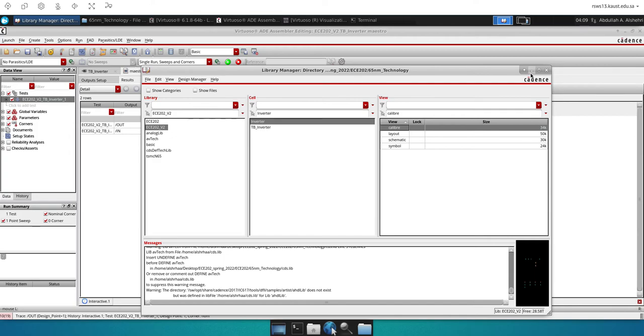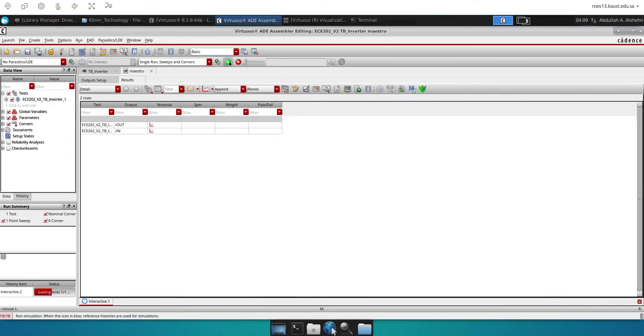We minimize this. Now we need to simulate and compare the design without taking into account the parasitic capacitance, the wire that adds more parasitics and resistance, and after we consider that parasitic capacitance. This is a small circuit, a small inverter, so the effect of this inverter will not be high. But once you have a big circuit, the OTA is considered medium size. You can see how you can design your circuit, because once you do the layout, you need to make sure how big the wire is that you need, and how far from each other. Also, there is parasitic between layer and layer, like floor and floor, not next to each other, but on top of each other. So you need to take into account all of those things.